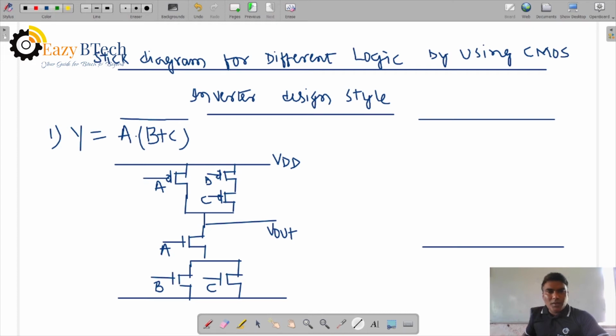After that we can draw the yellow color. First, when you are drawing a circuit, you can take enhancement. For the stick diagram, straight away we can take yellow color and join these two sources with the same yellow color, and here also. Drain and source are green. Transistor A is in series, right? And we have two transistors in parallel, the parallel representation.